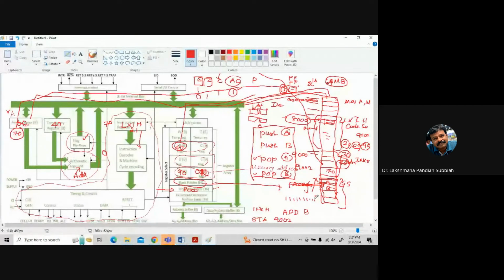Decimal change is actually, if you are having the value A, so here the value A is 10. The 10 in the BCD form we can have as 10. Instead of that A, we have to display the content as 10. So here we are getting the result as A, so 0A is the result. Now if you are adding 6, then what it will do is 6 plus 10 is 16, so 16 is here 0 and 1, so we are changing that. This is how the auxiliary carry will set.